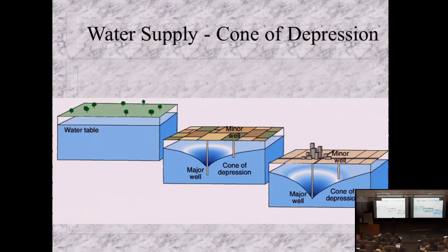And so these, I don't know if you call them unscrupulous, these bottling companies buy up a very small parcel of land, maybe an acre or something, put in a giant deep well and pump the heck out of it. And what is New Hampshire known as? The Granite State, right? So it's not sand, it's not an endless supply of water, it's fracture flow. The granite has to have cracks in it. And so those wells are quite low yielding, maybe 2 to 3 gallons per minute.